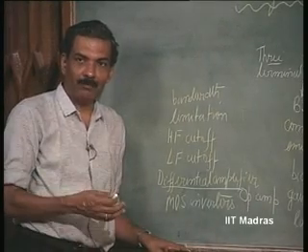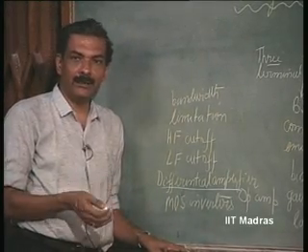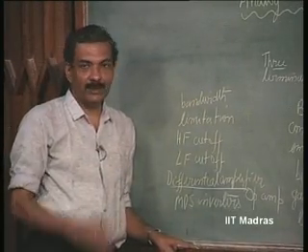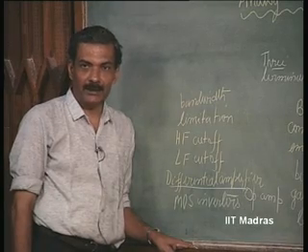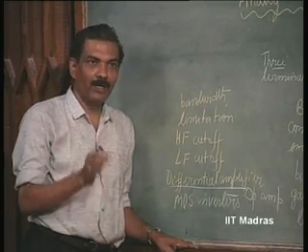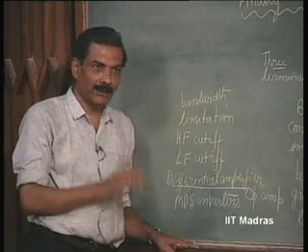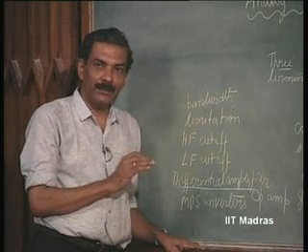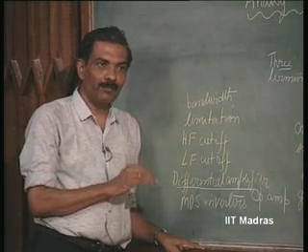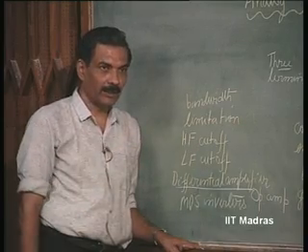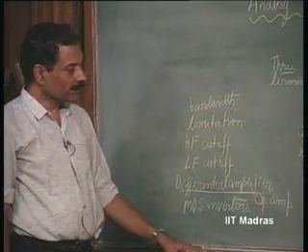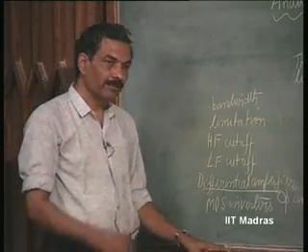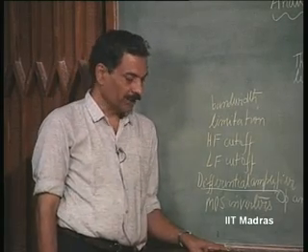So that in all these op amps we always try to increase the forward transfer parameter. Therefore, we get 4 types of op amps corresponding to the 4 types of sources or amplifiers which we have discussed, which are called operational voltage amplifier, operational current amplifier, operational transconductance amplifier, and operational trans resistance amplifier, wherein the concentration is always on improving the forward transfer parameter by cascading. We concentrated on the design of the operational voltage amplifier, and we saw how we can give an equivalent circuit for the op amp, the operational voltage amplifier.